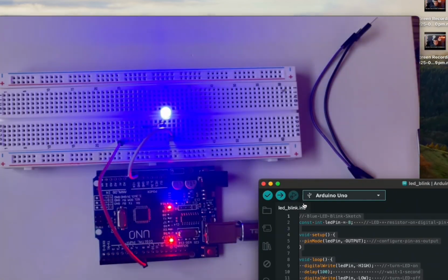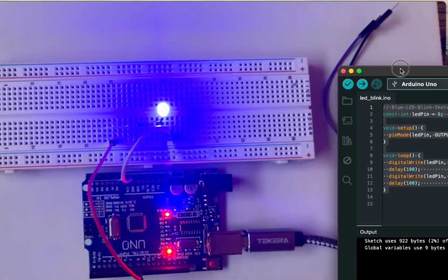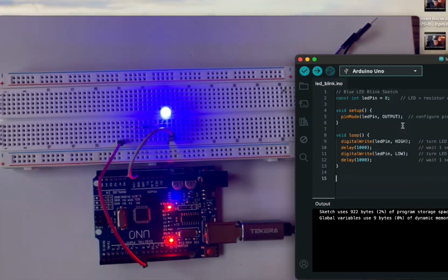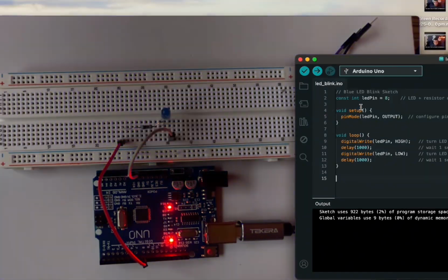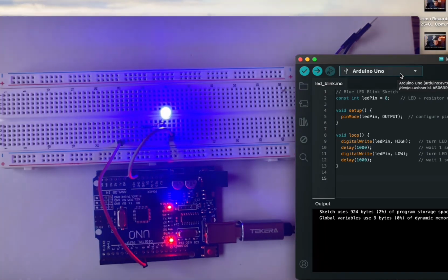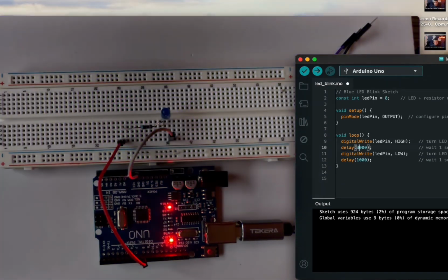The LED is blinking every 100 milliseconds. That's fun stuff. Disco lights. And now let's see if we can make it go slower, every 1 second. We just add another 0 over here, which means instead of every 100 milliseconds, it will blink every 1 second. So let's make it even slower. 3.